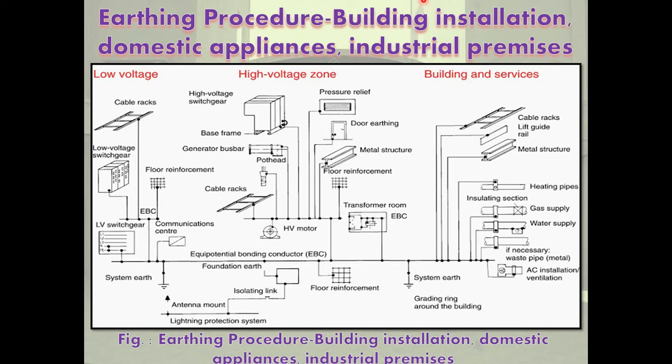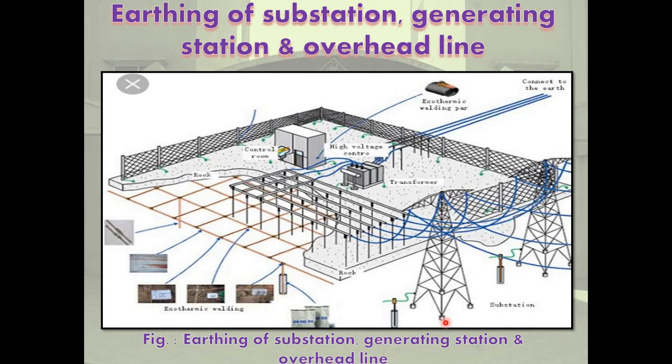Now, protective measures against lightning strokes on overhead transmission lines and outdoor substations. Lightning strokes are electrical discharges from charged thunderclouds to the earth. The voltage is 200 kV peak. A typical lightning surge is represented by a 1.2 microsecond to 50 microsecond voltage impulse wave, where 1.2 microsecond is the wavefront and 50 microseconds is the half time of the wavetail.